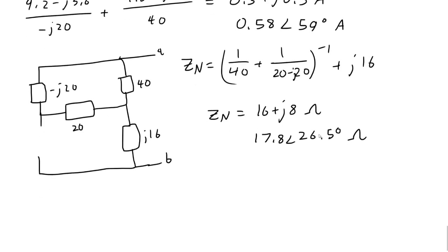Now, kind of like the last one, instead of it being a minus j, it's a plus j. That means that the impedance at this particular frequency, I don't believe it's given, but at this particular frequency, the inductive reactance will dominate. It's a primarily inductive impedance seen here. So this is probably at a high frequency, but we don't know.